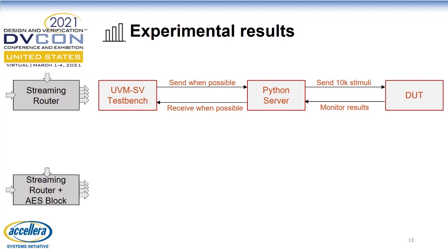To avoid as much as possible this overhead, it's better to buffer items and send multiple items within the same DMA access. This number cannot be too great, as resources on the FPGA side are also affected. We chose 10,000 stimuli to be sent, which is an arbitrary number to reduce DMA accesses, without using too much FPGA resources.